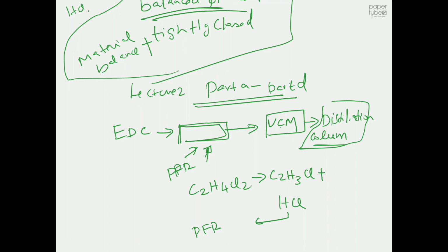So at the end of the day you will get a pure vinyl chloride monomer, and then we will check how efficient our process is, whether we are nearing the stoichiometric efficiency. Say you start with 350 kilomole per hour of ethylene going into the process, and we will check whether we are really getting 350 kilomole per hour of vinyl chloride monomer from the process.